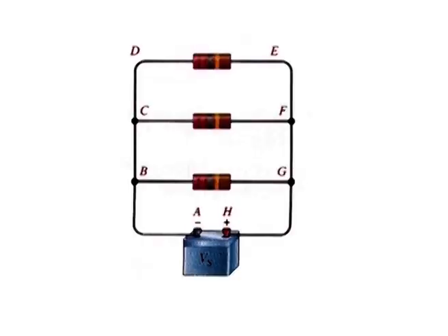Voltage in a parallel circuit. The voltage across any given branch of a parallel circuit is equal to the voltage across each of the other branches in parallel. Each circuit path in a parallel circuit is called a branch. To illustrate voltage in a parallel circuit, let's examine this figure. Points A, B, C and D along the left side of the parallel circuit are electrically the same point because the voltage is the same along this line.